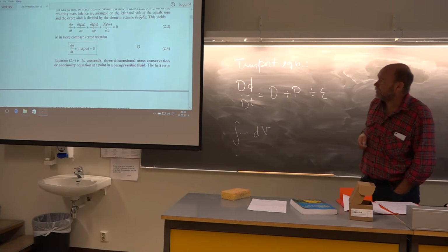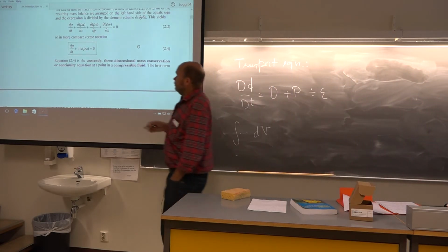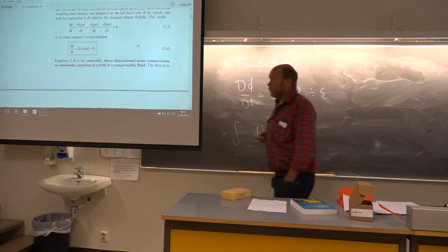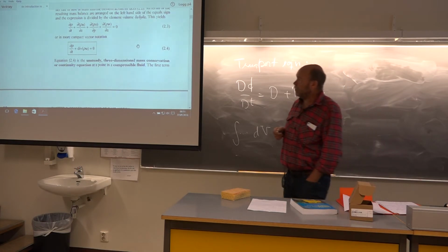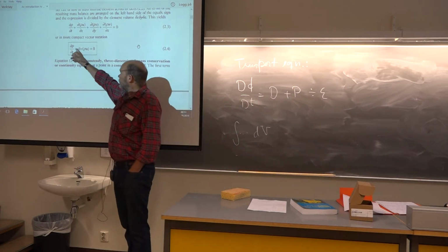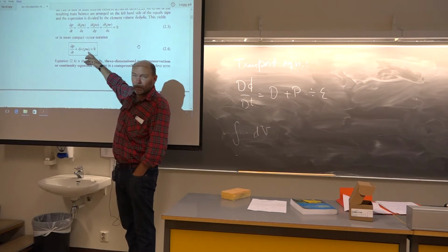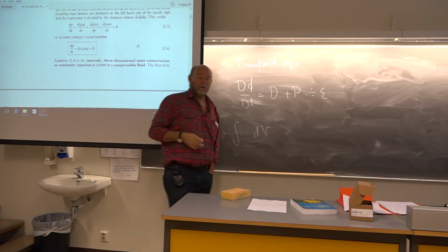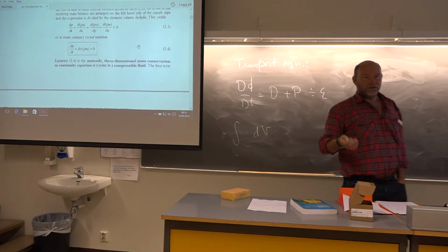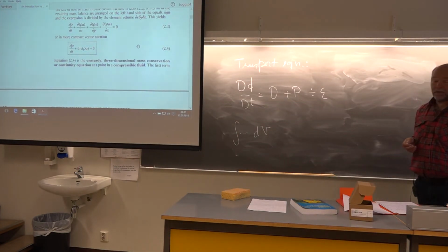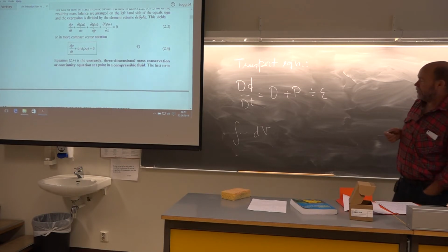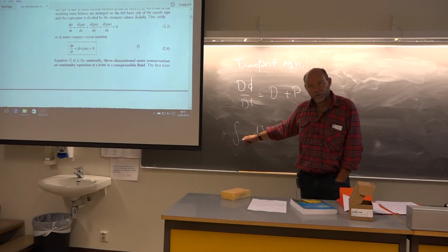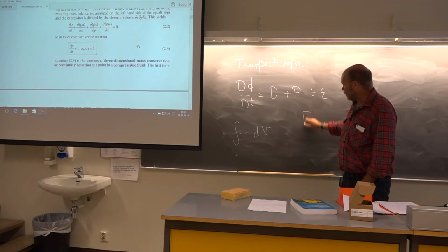And the reason I don't like it is when you have it in this form, then you have the demand for any variable here. The density and the velocity vector, they have to be continuous functions. You must be able to create the derivative of them. You're not allowed then to have a sudden jump in velocity or density like with a shock wave. But if you have it as an integral formulation, it covers more physics inside one single cell.